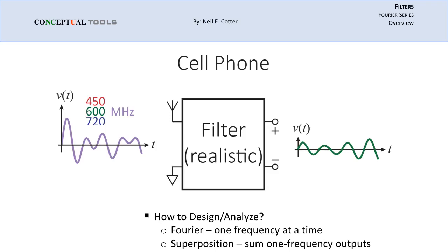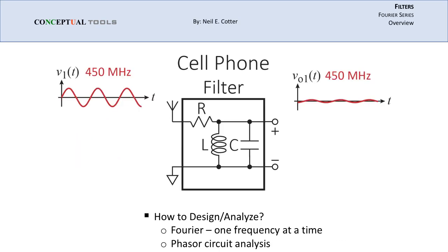The idea is that the signals coming in, the sinusoids, act as though they each are in their own channel, and we may analyze what happens in that channel separate from the other channels, then add up the results to get what happens when all signals are present at once at the input. Let's consider in more detail the process of analyzing each input sinusoid one at a time.